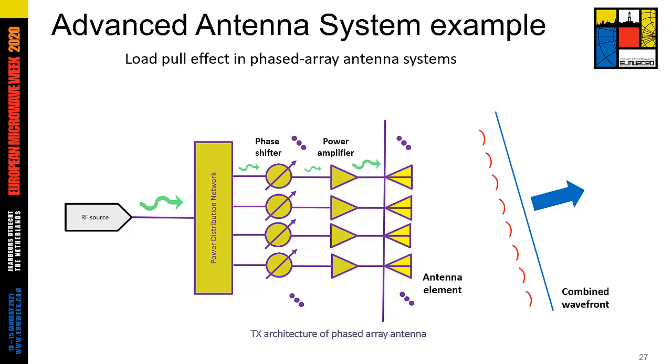By controlling the phase shifters, the system makes it possible to steer the beam in a specific direction. Currently, the antenna is designed from ideal signal magnitude and phase at the input ports of the antenna. After manufacturing, a set of measurements in an anechoic chamber allows calibrating the antenna, that is to say, applying a new control on the phase shifters that takes into account the impairments of the system and so corrects the beam direction of the antenna.